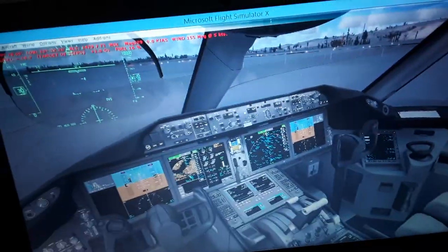So we have also the onboard antennas that receive the LSZH localizer, and we have also to align with the magnetic north pole heading. So we have the Zurich International Airport runway 14. We're going to be aligned with the runway 14 magnetic heading and LSZH frequency. We have also the LSZH localizer crossbar. We have the flight director crossbar for manual guidance of the aircraft, and the autopilot crossbar for automatic guidance of